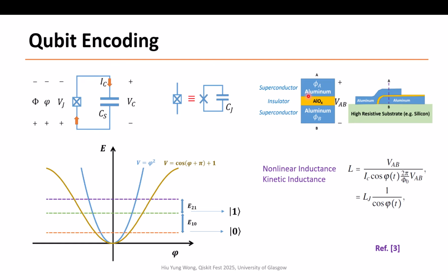The interesting thing is that we won't go into detail, but they come up with something called the Josephson equation. More importantly, you use the Josephson equation, you have the current and voltage relationship, and then you find that it does store energy, and it also has inductance. This inductance is called kinetic inductance, but more importantly, it is non-linear.